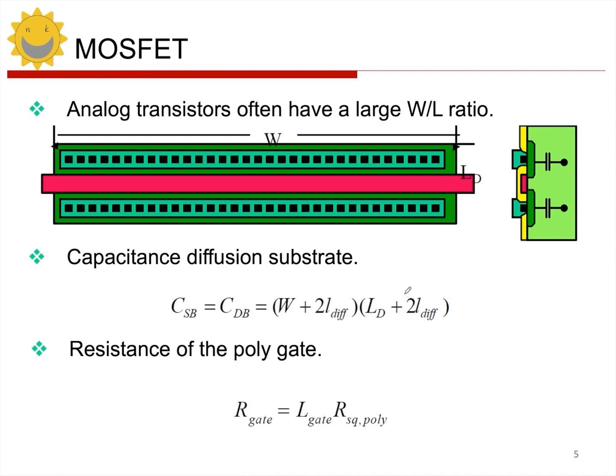So what should we do? Some students might ask, can I just add more contacts on the gate, just like I did with the source? I added contacts there. I also added a row of contacts on the gate, and then covered the entire gate with metal. This way, the voltage gets transmitted through the metal, reaching the gate in segments, right? So the signal that the gate receives becomes very reliable. If we do this, then in theory we can solve this problem, right?